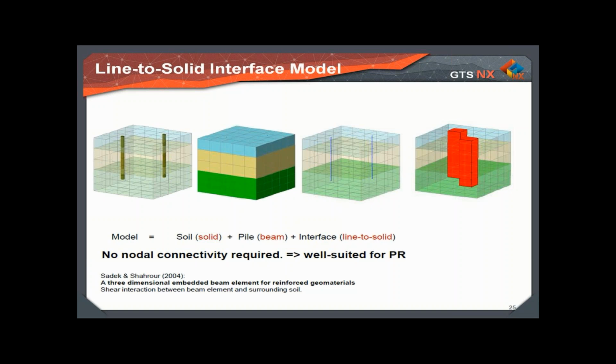Here I have to mention that this idea of embedded pile techniques goes back to the beginning of 2004. There was a publication by Sadek and Shahrour, who worked on a 3D embedded beam element for reinforced geomaterials. It was meant for reinforcement like anchors and things like that, and this was utilized here as a pile element. So there was some modification, mainly the addition of the interface and the tip interface, and the tip element, to become a pile element.